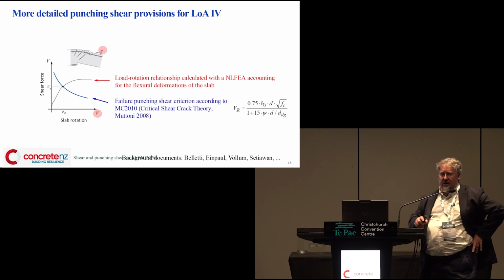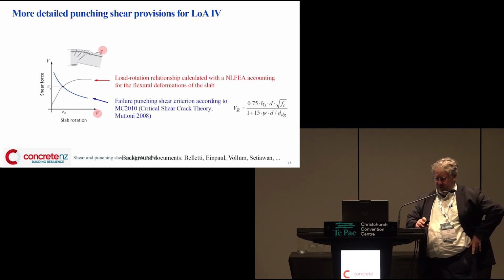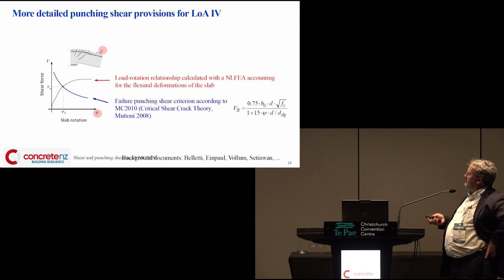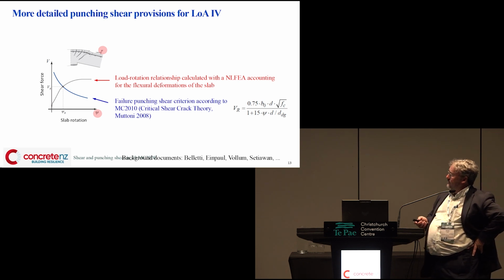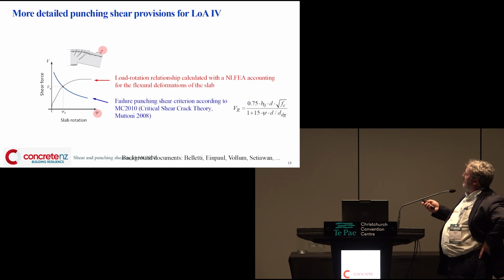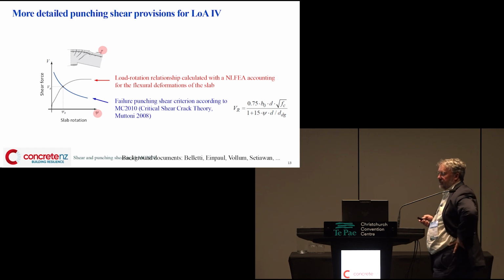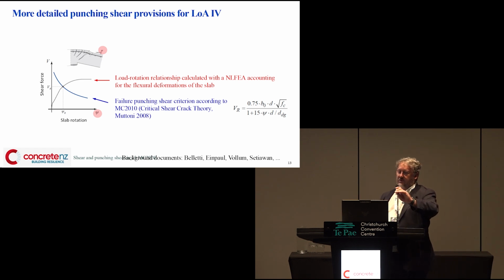Now, just this last slide, it was an example of Aurelio's where they had to look at a parking structure, a real structure, and again, assess its current capacity. Without going into too much depth, this is essentially the load path here. If you use the lowest level of approximation, in this case approximation 2, you get a result here of a bit under 3,000 kilonewtons for its capacity. If you go to the higher level and include the membrane action, we're getting pretty close to the optimal. And then if you go to a higher level again, you get the most optimal.